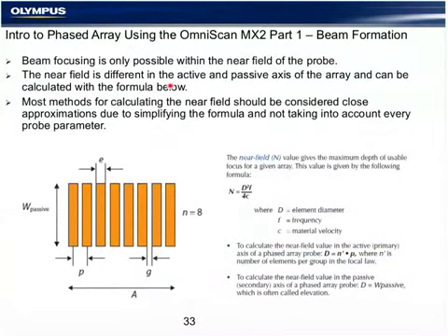So if we were to pull out our calculator, which in phased array we don't necessarily need in our day-to-day business, for any given probe's aperture, the number of elements being used times the size of those elements and the frequency, you can arrive at the theoretical near field calculation. The near field distance is the maximum distance theoretically from which beam convergence or focusing can happen.